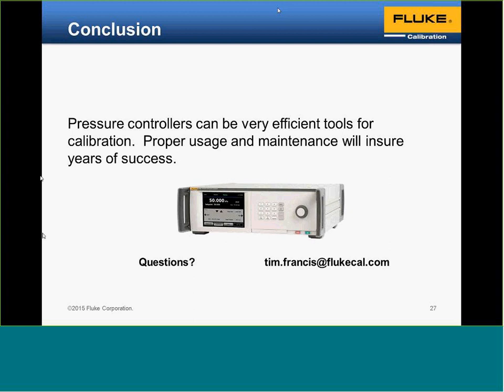Most controllers' user manuals will provide specifications on how clean and dry the air needs to be, and there are dryers and filters available on the market. If you're talking to a supplier of gas bottles, those specifications will allow you to make sure that they're providing you the right supply gas.